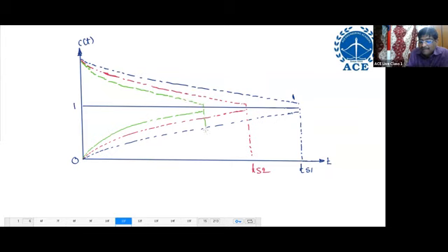This is for TS3. So what happened? 3 envelopes. So settling time decreases because time constant decreases. Next, the imaginary part is the same. Imaginary part same means frequency of oscillations are the same. Now draw the frequency of oscillations for 1 and 1 dash. First draw for 1 and 1 dash.